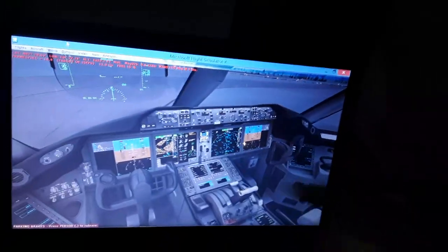So using the left and right wing, it is going to be calculated how much fuel we have: 30% in the left and 30% in the right wing tank, 10% in the center tank. The flight management computer, as I told you, calculates the loads. So we're going to have the center of gravity, the minimum aerodynamic chord position of the forward wings, and the horizontal trim stabilizer for takeoff. With the center of gravity, it is going to be 4.35 degrees